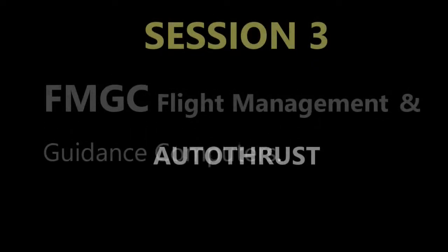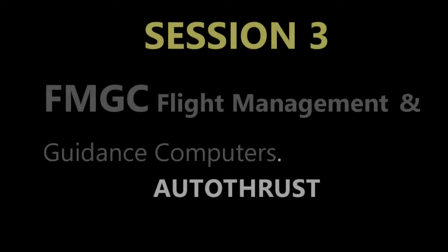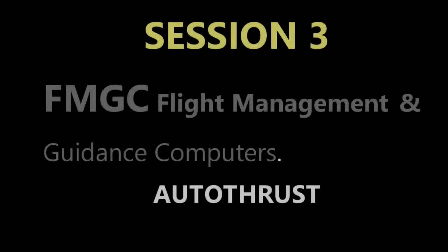So that's what you have there with the warnings. Okay. I just want to go a little bit on auto thrust and mention some things with the auto thrust. Auto thrust, this is in relation to flight guidance, okay, on the FMGC. With your auto thrust function, this is going to send a command to the FADEC. Because remember what I said about the whole thing on Autoflight system, it's also about sending signals to FADEC, okay, for engine control. And so here, this is exactly what the auto thrust is about.